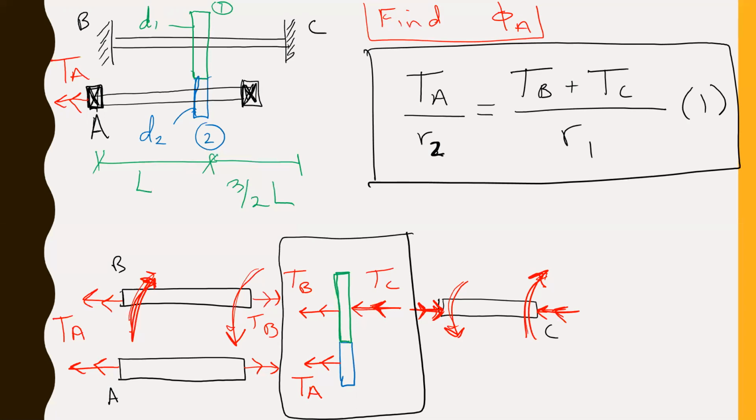So if you start at point B at a certain orientation, you twist that rod between point B and the gear, that's some twisting that, if we were to look at it from this side, we're over here looking this way, that twisting would look as though it were twisting counterclockwise. Whatever magnitude that is, we then need to unravel it by twisting the other direction, that same angle, to get back to C, because initially that shaft went straight across from B to C, and everything was in the same relative orientation.